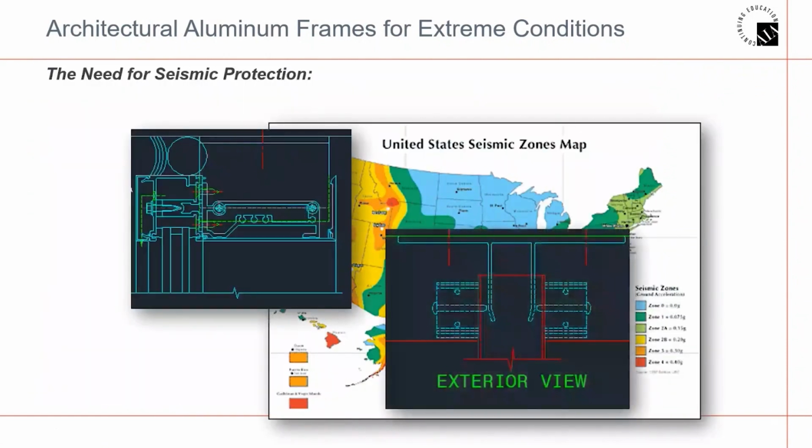Typical curtain walls are designed to float on the head and sill anchors. Typical F&T anchor is hard fastened to the surround, while the verticals slide up and down over the anchors. This type of attachment allows limited movement of the curtain wall within the elevation while remaining secure in the opening, protecting it. A typical perimeter joint around a curtain wall is 1/2 of an inch.